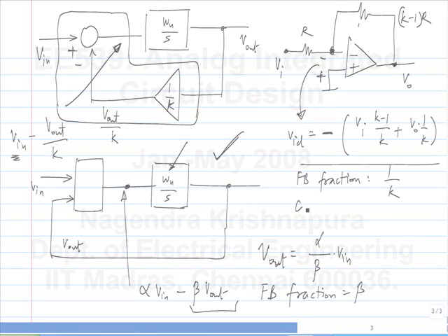What is the closed loop gain? Okay. So again, this is roughly like changing the zeros of the transfer function by applying the input to different points. Okay. You can change the numerator. But the loop has not changed. So for instance, I make a non-inverting amplifier, and in absence of the input signal, it will look exactly the same as this, right?